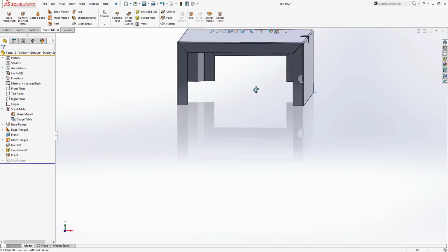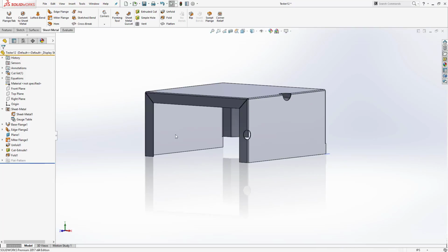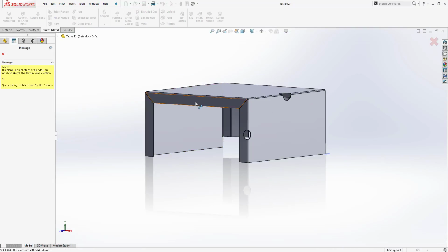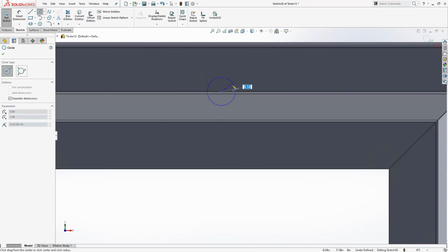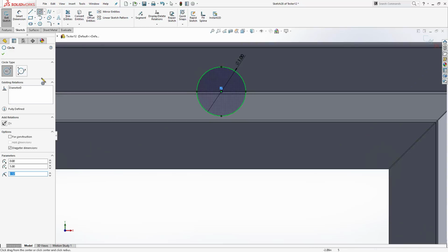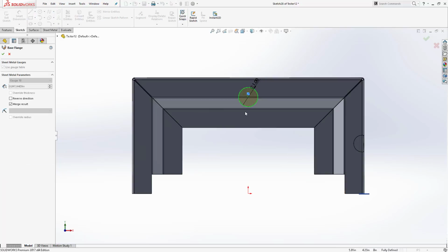Okay. So adding material to something that's already there. Maybe we want to add a tab onto this thing, right? Tabs are used when you don't need to add a bend. You're just adding material. So maybe like that example I showed, you want to add a circle piece onto this thing. So we'll go ahead and, again, just go in here. We'll just snap it to this midpoint and make it a nice clean 1. A lot of hard numbers working with today.